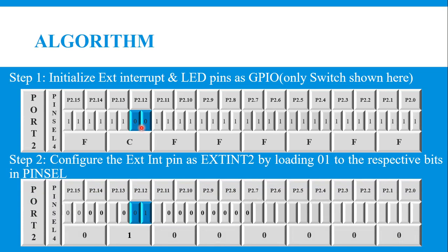I will move 01 into pin select register 4 at the corresponding bits of P2.12, then it works as external interrupt 2.